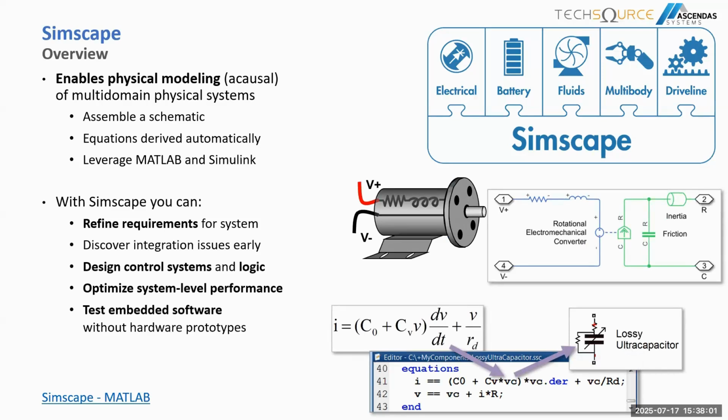You can parameterize your models using MATLAB variables and expressions as you always do in MATLAB or Simulink, and put it in as an application in Simscape, and then design your control systems, in this case, to provide physical systems to Simulink. And then later on, you can deploy these models, for example, in your hardware in the loop systems. So Simscape supports C code generation for you to be able to deploy in hardware in the loop testing that you do within your testing capabilities.